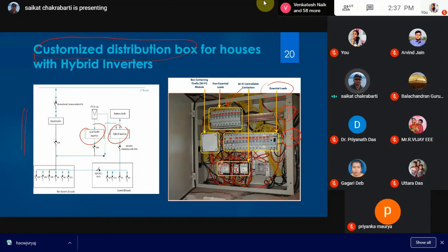So in the utilities or at the main substation, if we are going through a peak demand period, we can control these devices through these Wi-Fi control level switches, which are placed in this distribution box, and also adjacent to the appliances. Okay, wherever the switches for the appliances are there. So we have a small wireless module connected to each switchboard within the house, and from those switchboards we can actually control the appliances. So that's how we are able to implement demand response, right?